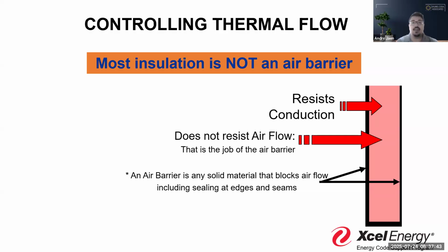Well, then we use that opportunity to try and make sure that we have proper evaluation of what is our total assembly, right? It's a good thing to talk to the contractor about and say, do you have any exterior insulation, right? Oh, no, it's just cavity, it's just pink stuff. Okay, well, how's the pink stuff doing? Well, we found some rot in some places. Well, that's a good cue for you. It means it probably doesn't have great air sealing. So that's a great thing to talk to them about.